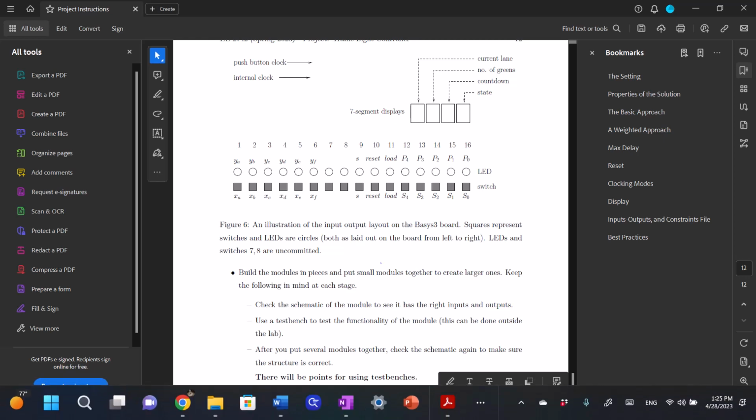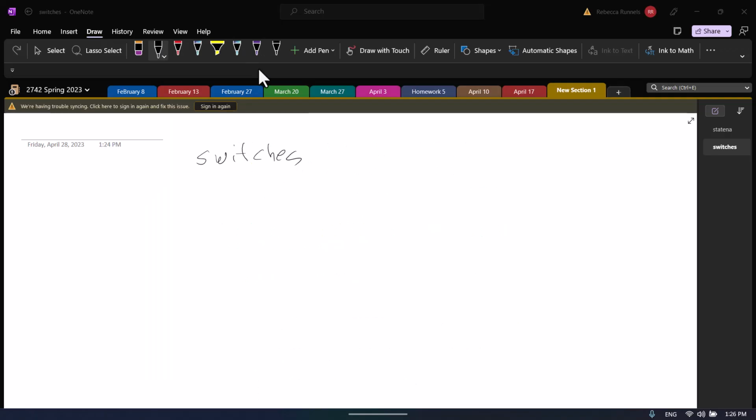You can do that as a vectored signal. So when you put that in, you can do it as input [4:0] S. And when you're putting it in your parentheses for all your inputs and outputs for your module name, you just need to put the capital letter S. Putting it in this order will help you when you define your switches.